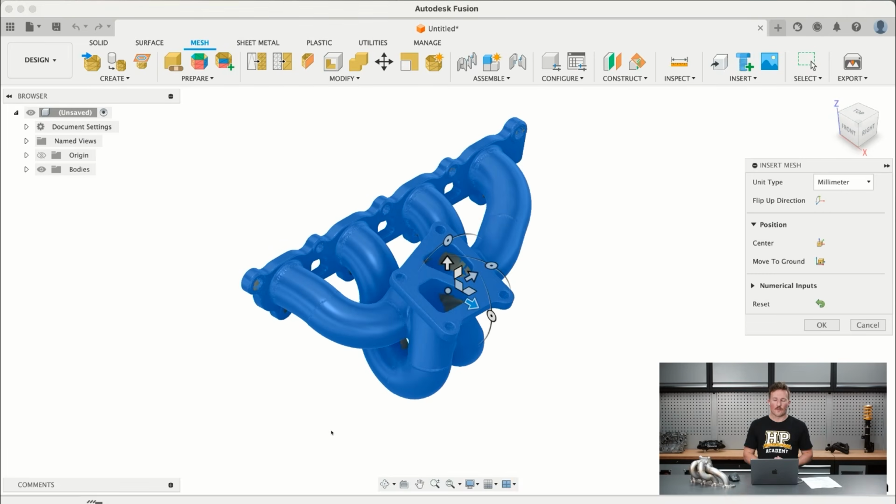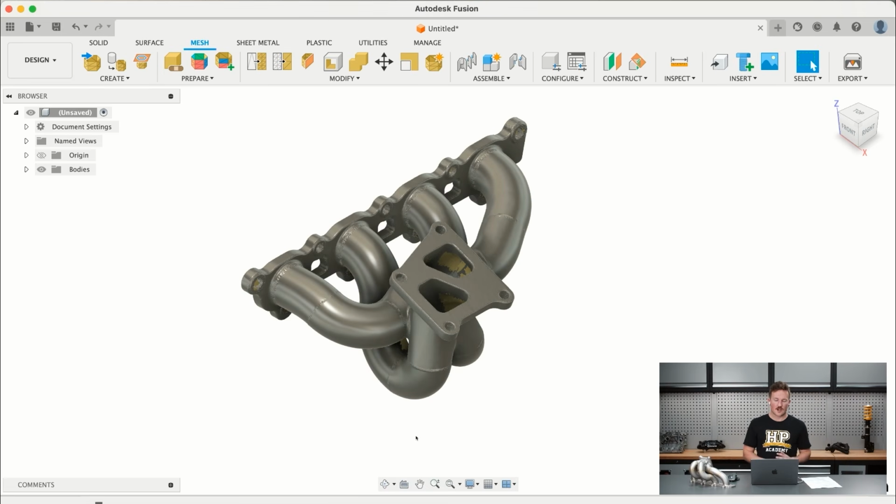And this is the more basic way to do it if we're just working with a mesh file that we've got out of a scanner and we don't have dedicated reverse engineering software like PeelCAD to then transfer it over to our CAD software, being Fusion in this case. This is the alternative, but maybe the more accessible approach as well. So we'll just show that first.